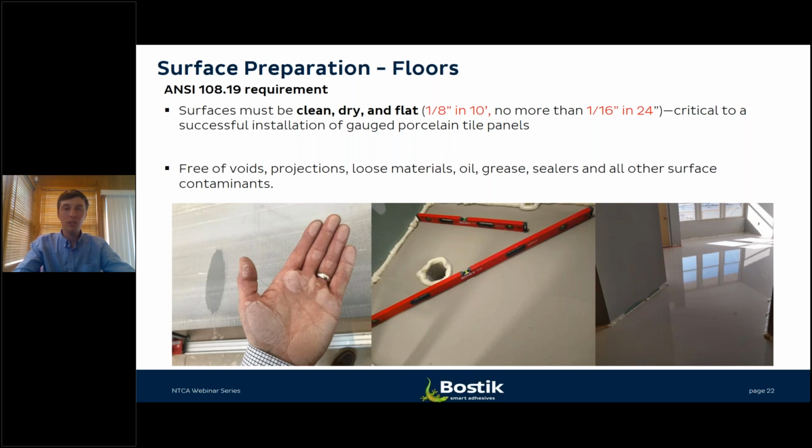In the next couple of pictures at the bottom of this slide, you see a variety of self-levelers that have been used to flatten floors. This is a rapidly growing category in the world of surface prep and tile, achieving flat floors, as we have larger format tiles like these gauged porcelain tile panels. Even large format tiles, by definition, are tiles that have any side over 15 inches. So a 4-inch by 16-inch tile fits the category of a large format tile.